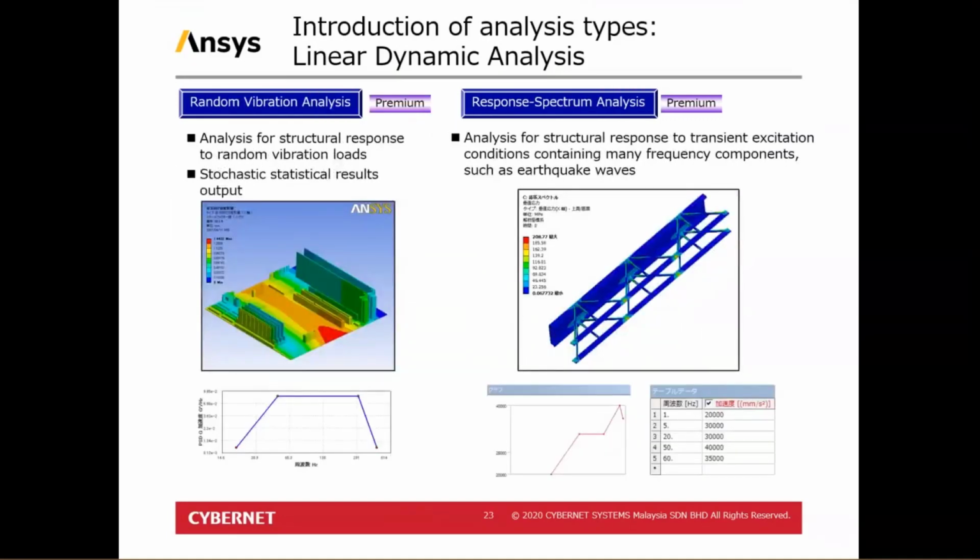So we're still with vibration analysis. Next, we have the random vibration analysis and also a response spectrum analysis. For the random vibration analysis, this is basically an analysis for structural response to random vibration loads. This type of analysis is used in case when the input is non-deterministic.